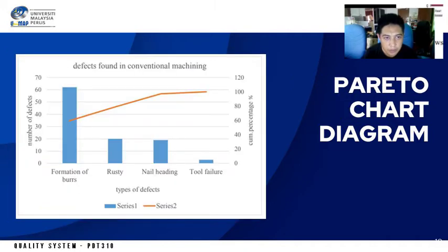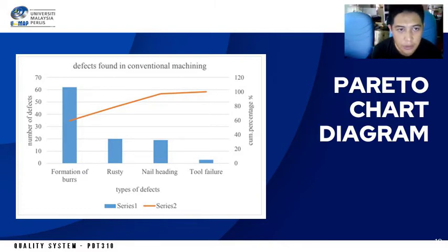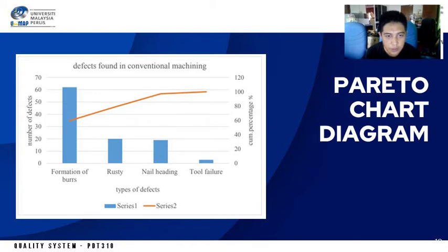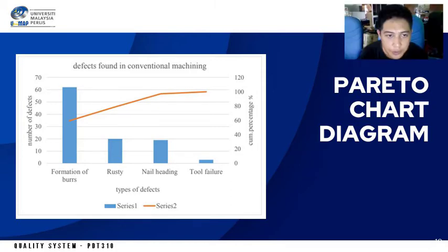Next, for the Pareto chart, determine the method of classifying the data by problem, cost or type of non-conformity. Decide whether weighted frequency or frequency is to be used to rank the characteristics. Collect data for an appropriate time interval. Summarize the data and rank order it, categorized from smallest to largest. Compute the cumulative percentage if it is to be used. So this is the method for constructing the QC tools.